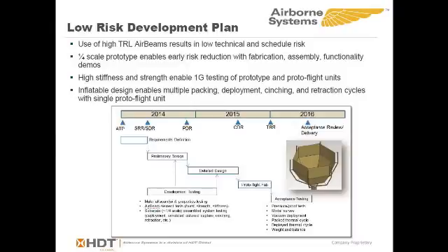The second thing is that since this is a very stiff structure, it can be used very easily in a 1G environment. And we're proposing a proto-flight system. In other words, the qualification unit is also the flight unit. And so this unit could be packed, deployed multiple cycles, and go through all the typical testing you would want to have it go through to prove out the reliability of the system.